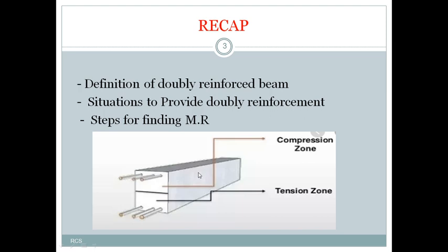The second option is increasing the limiting moment of resistance of the beam by providing reinforcement. If you provide additional reinforcement in the tension zone, it will become an over reinforced section. As per the recommendations of IS 456-2000, over reinforced sections are not designed and are not advisable because they are unsafe and uneconomical. So the only option we have is to provide reinforcement in the compression zone. Then we can increase our limiting moment of resistance so that we can make our section stable and resist the bending moment due to the externally applied force.